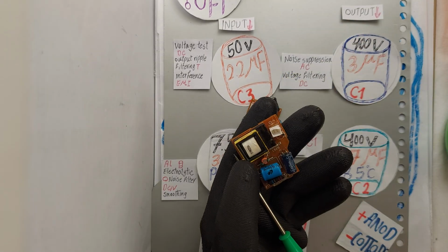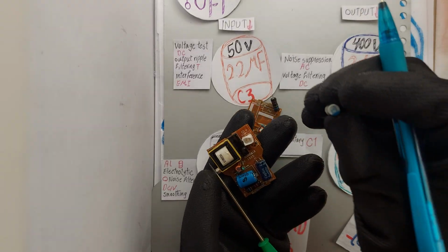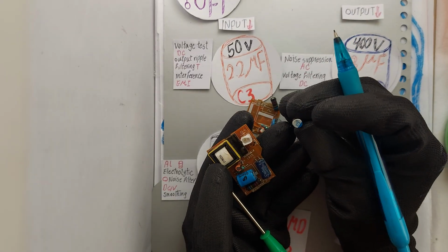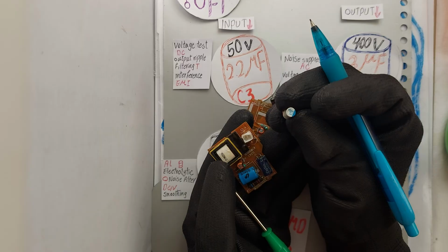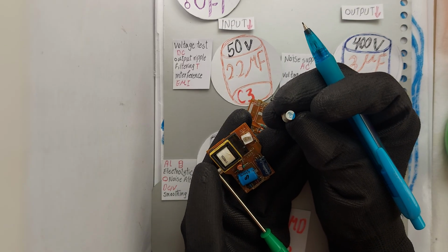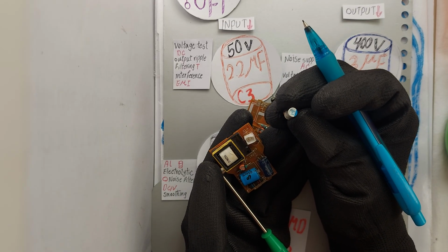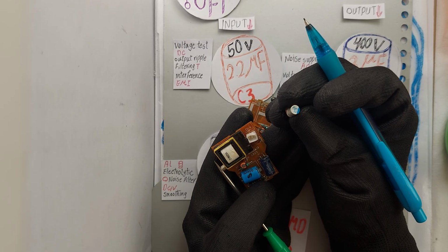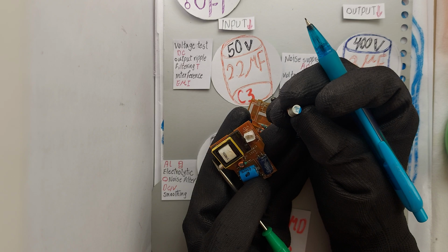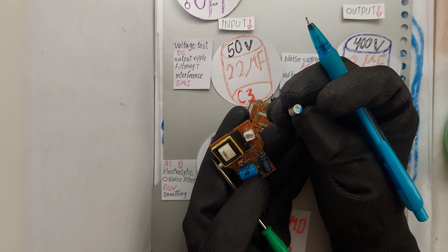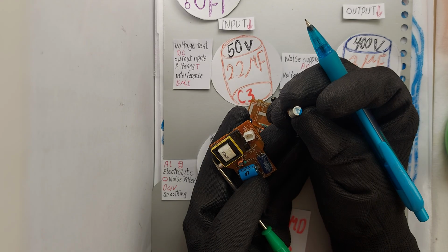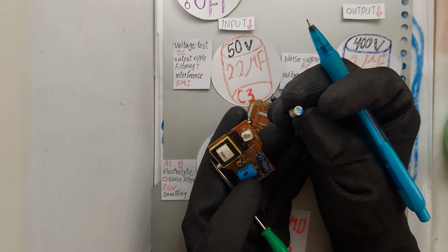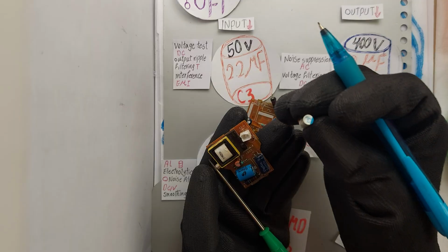And now we came to capacitor 4, as you can see right here. This cylindrical aluminum electrolytic capacitor with high capacity is on the output side. It filters residual noise and smooths the DC voltage. Its 390 microfarad capacity ensures the charger's output is resilient to sudden load changes and provides stable voltage. Its 7.5 volt working voltage matches the circuit's low output.